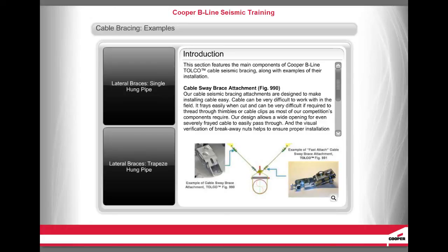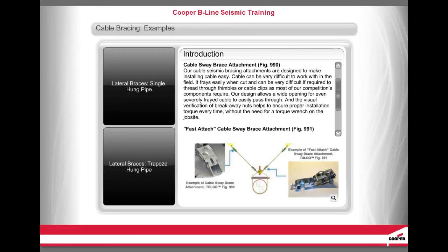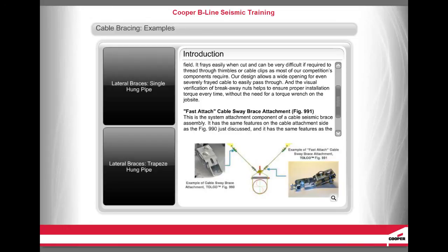Our design allows a wide opening for even severely frayed cable to easily pass through, and the visual verification of breakaway nuts helps to ensure proper installation torque every time, without the need for a torque wrench on the job site. Fast Attach Cable Sway Brace Attachment, Figure 991.